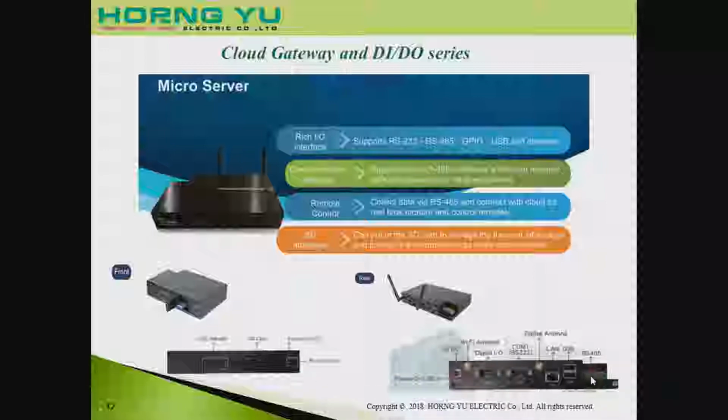For the gateway we support RS-485, which allows all components with the same RTU Modbus protocol to connect through our gateway to transmit data and go online. Also we support Ethernet, so this gateway can be put inside the panel to get an internet connection.